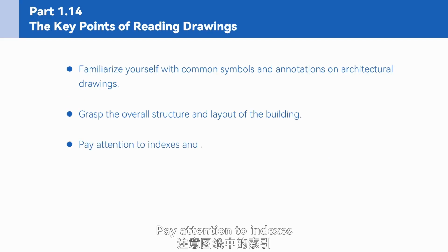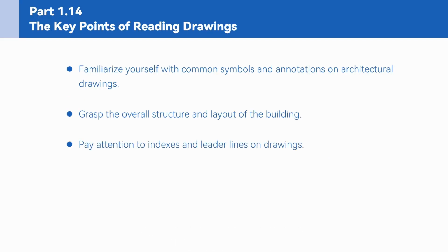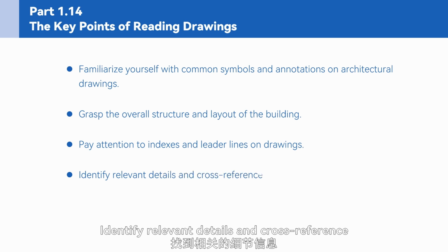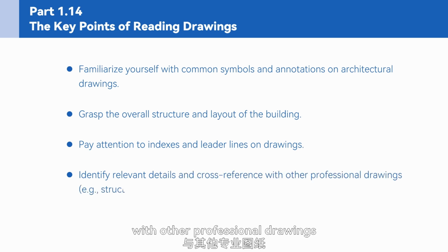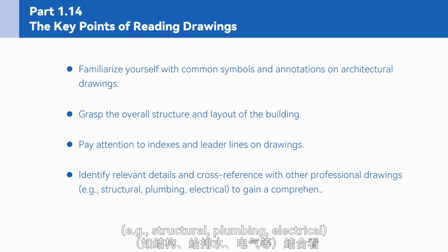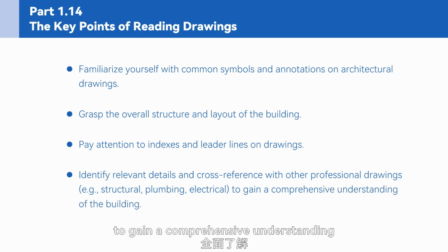Pay attention to indexes and leader lines on drawings. Identify relevant details and cross-reference with other professional drawings, e.g., structural, plumbing, electrical, to gain a comprehensive understanding of the building.